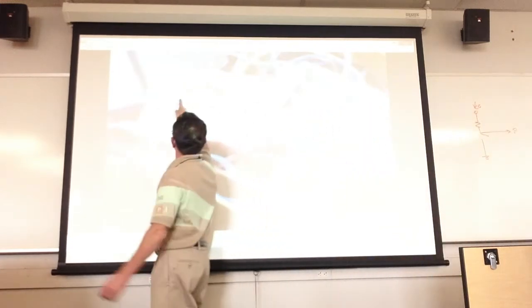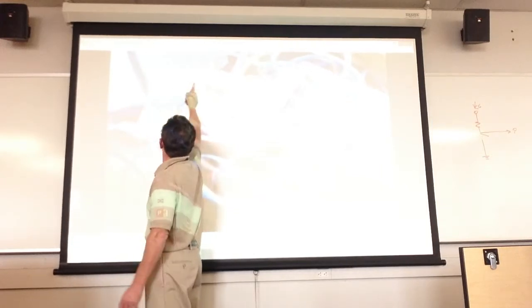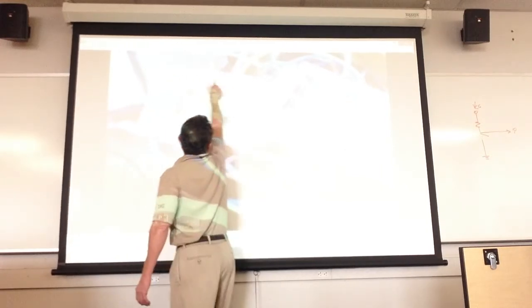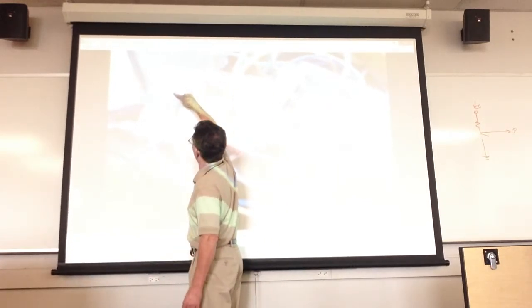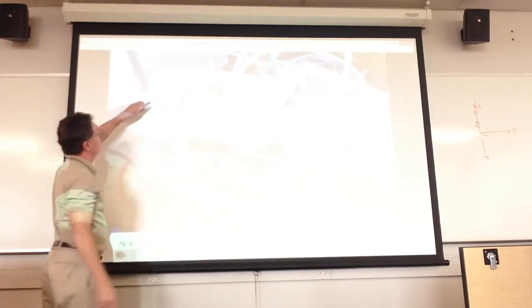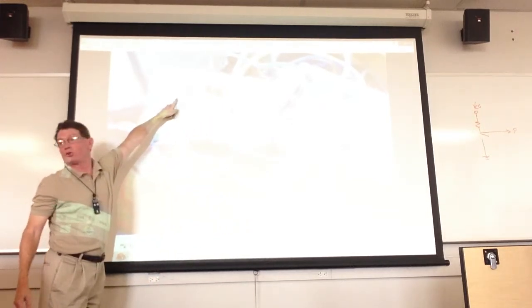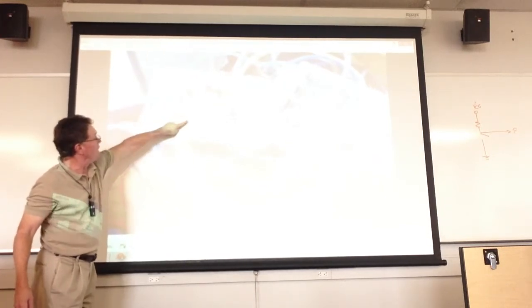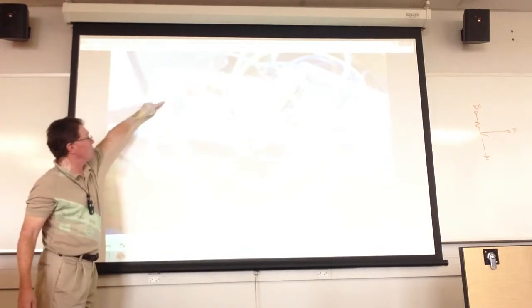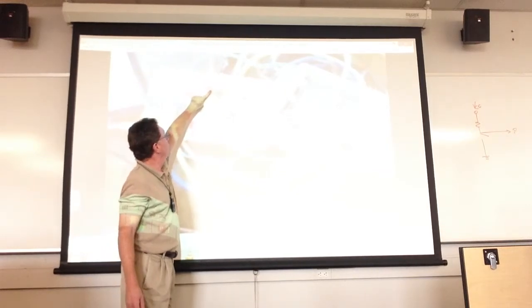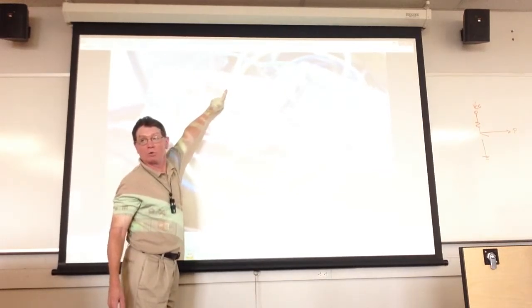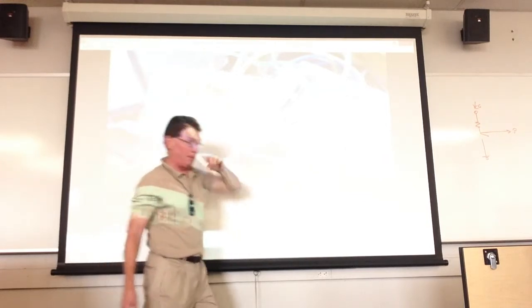So what you see here is my dip switches over here. I could have used any one of these. If you notice all these little yellow wires, ground is on this rail back here. All that is ground back there. Here are my switches that I can throw, and I think I only used one, the first one. I'm on port D, pin 0 is what this is tied to. And I actually have the scope on it also. This is port B, pin 0, pin 1, pin 2. We're going to write to the third LED, which is on pin number 2.